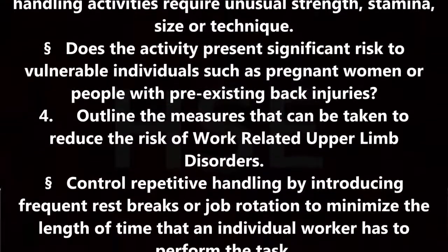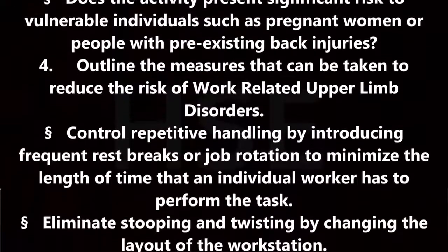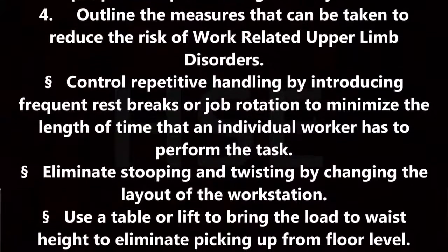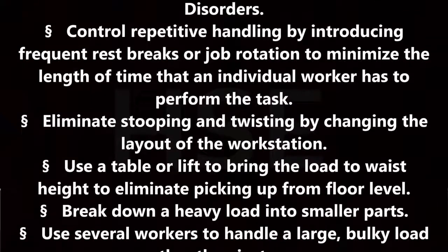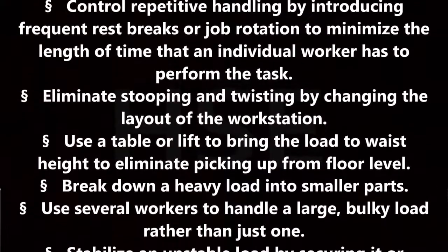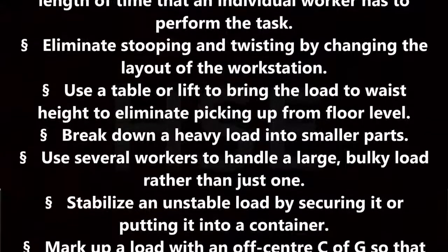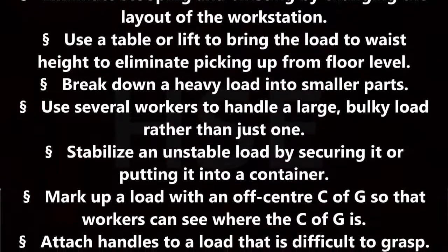Break down a heavy load into smaller parts. Use several workers to handle a large, bulky load rather than just one. Stabilize an unstable load by securing it or putting it into a container. Mark up a load with an off-center C of G so that workers can see where the C of G is. Attach handles to a load that is difficult to grasp.